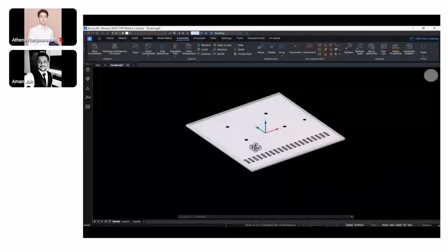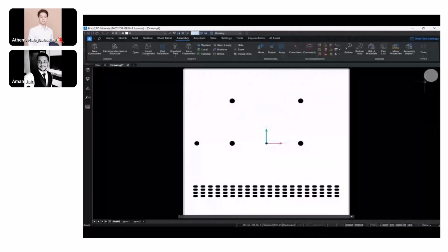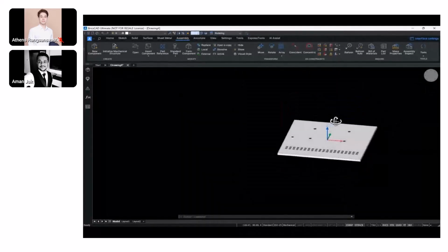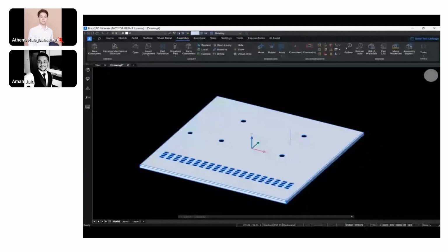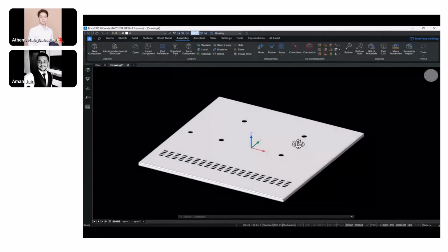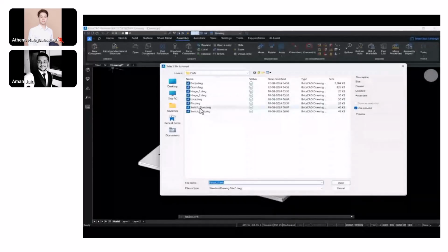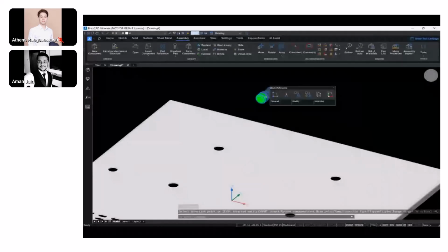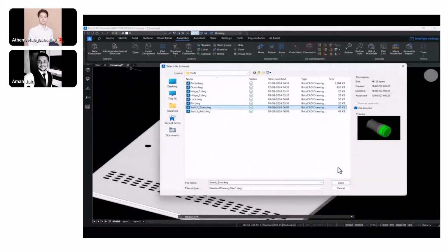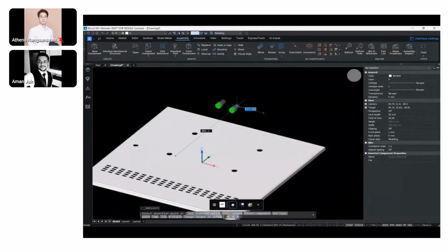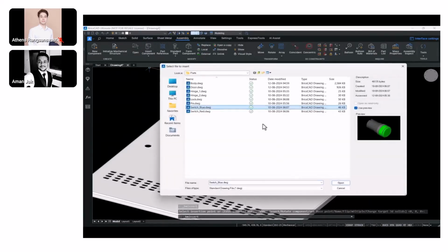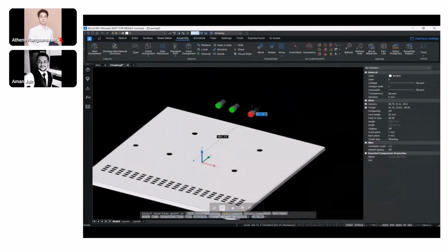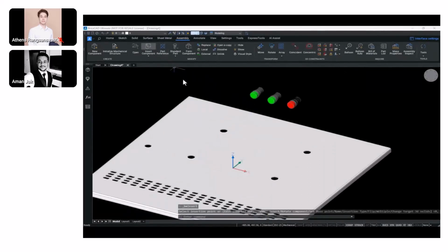And then we'll try to add more components, like I was mentioning earlier, the switches for our door and also the lock. Okay. So again, we'll use the insert component, or you can even type in BM insert on the command line, which essentially executes the same command. You can go in from the ribbon, or you can use it from the command line, depending upon the comfort level of the user. So it really becomes handy for someone who's coming from a CAD background, who's very used to using the command line rather than the ribbons. Right? So it's really handy for them to be able to execute the commands that they want through the command line, even for the 3D operations that they do.